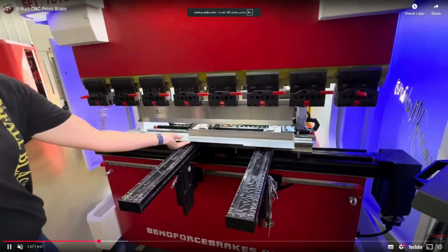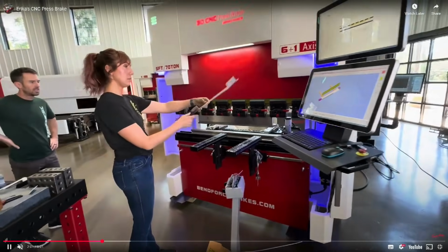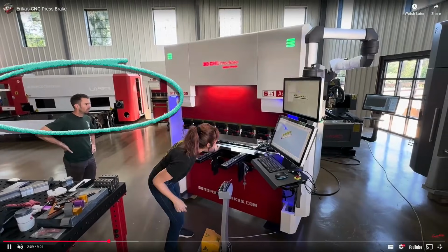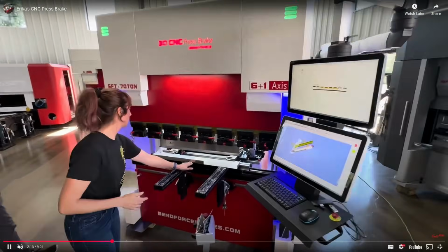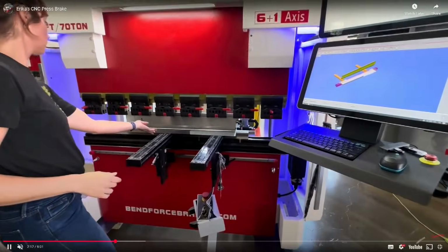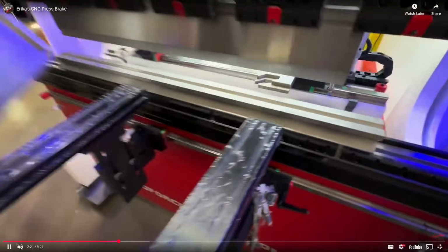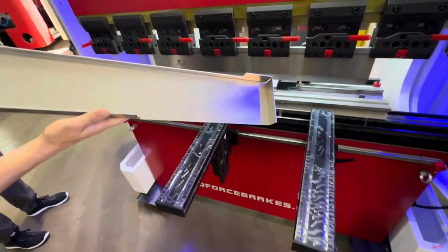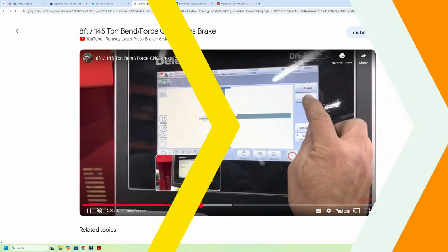Let's make that full screen. There you are. It bends it up so the form is big enough to do the job. Nice clean bends. Got a laser cutter on the side here, that you see on the left hand side. Puts them in, these two stops, perfect for the job. These are sometimes magnetic. They've got this film on it to stop it scratching the material. There you go. Perfect fold. And if you wanted to, you can weld those corners up that you see there.